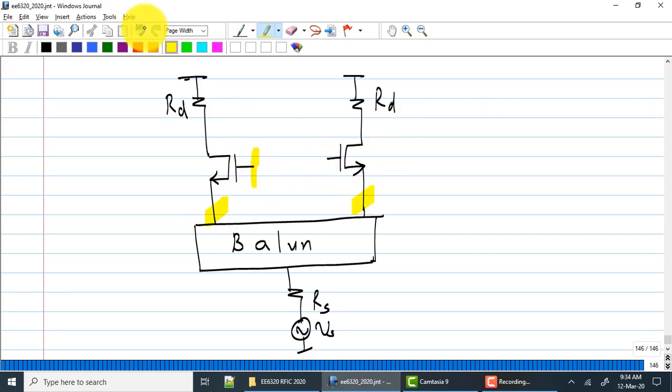It turns out that you can also do capacitive coupling, because I have a fully differential circuit. Because I have, let us say, plus V in, minus V in. What I wanted was negative feedback, such that I got some minus A times V in here. In this case, I'm just giving A equals 1, so I'm giving minus V in from the negative side of the circuit.